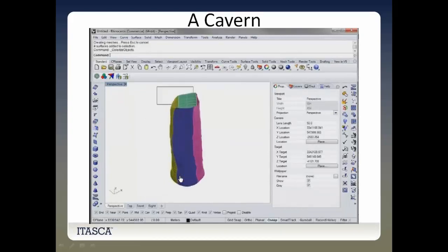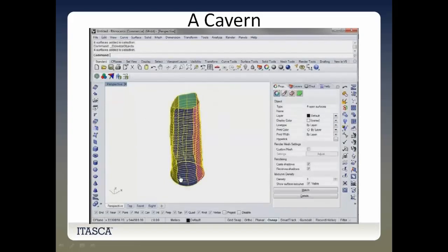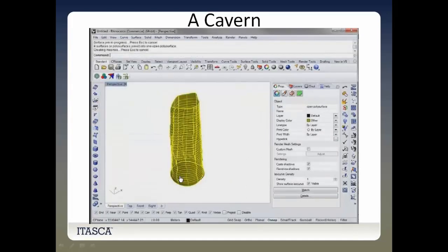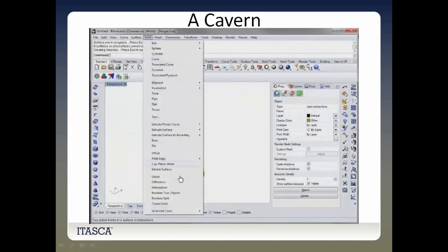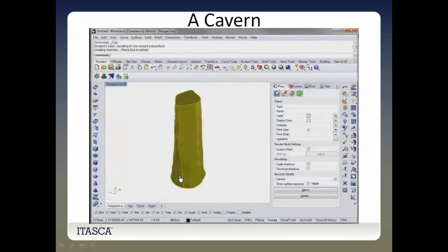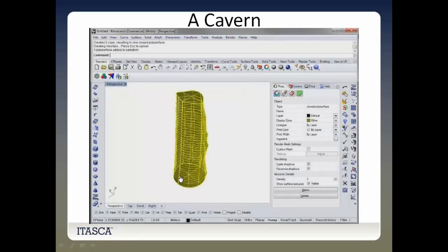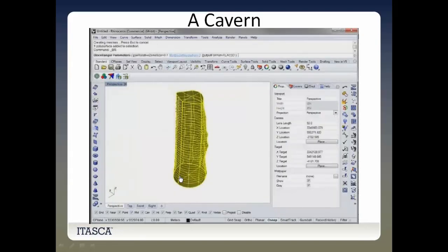Now you can see that this surface has been broken down into 4 faces, and now I say just join them all together and cap it. So now this object has really 6 faces, and so it's a candidate qualified for BlockRanger. I click on the BlockRanger command.